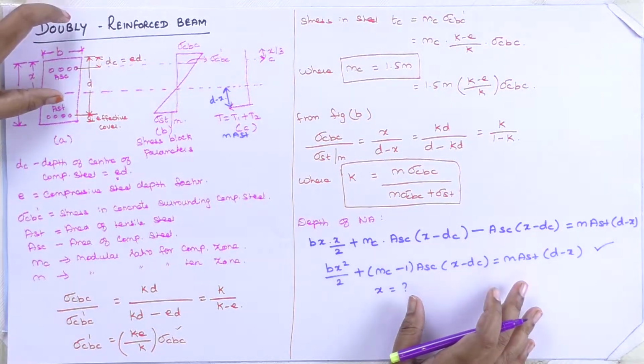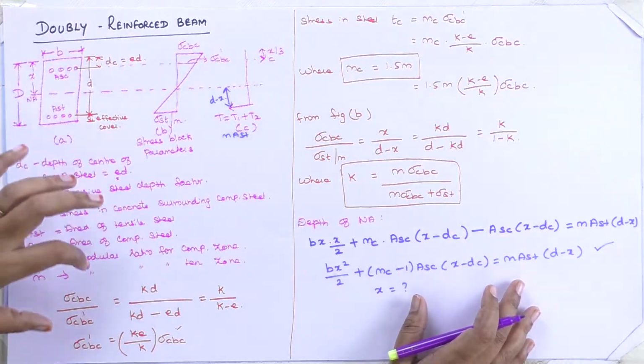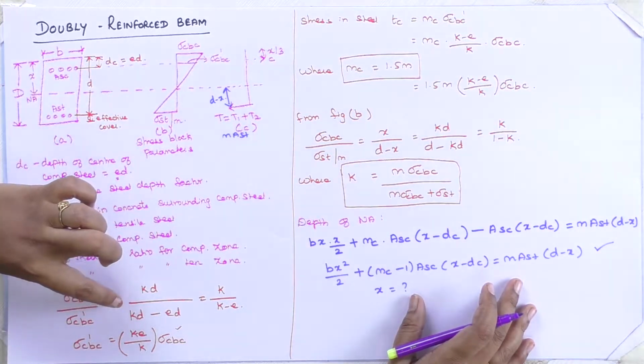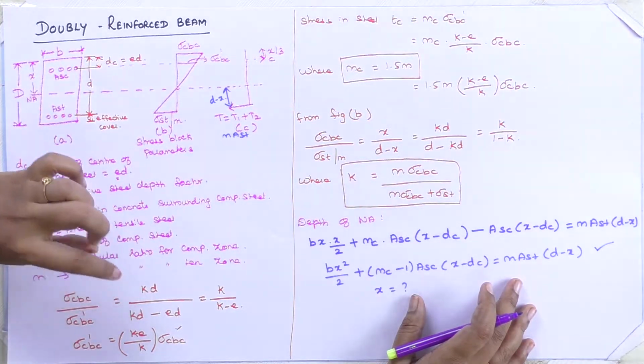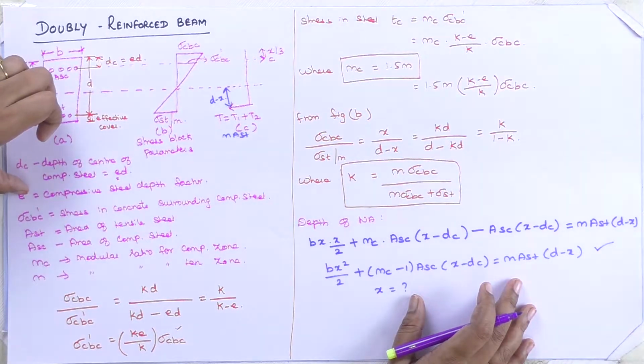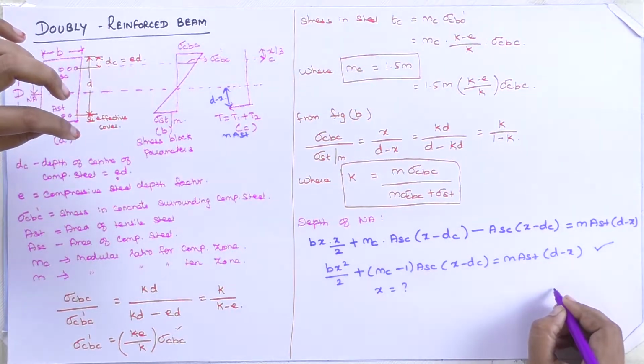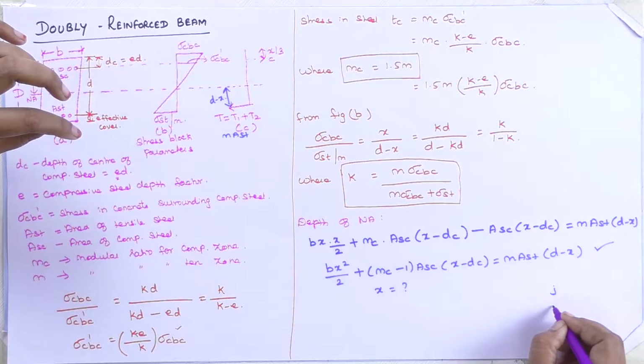Okay, this is the analysis to calculate the design constant values. Here the extra design constant when compared to a singly reinforced beam is e, which is nothing but a factor. In the singly reinforced section we calculated some factors, that is the lever arm factor j, then k.